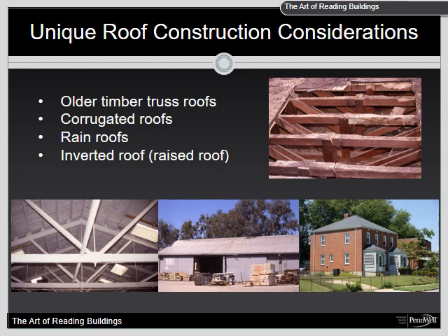Fiberglass, aluminum, and steel corrugated roof panels can look the same from the street, but they will react differently when exposed to heat and fire. Use a roof ladder or aerial device to distribute the weight load if it is necessary for a person to be on a corrugated roof. If a corrugated roof has fiberglass daylight panels, they will quickly fail if exposed to heat or fire.